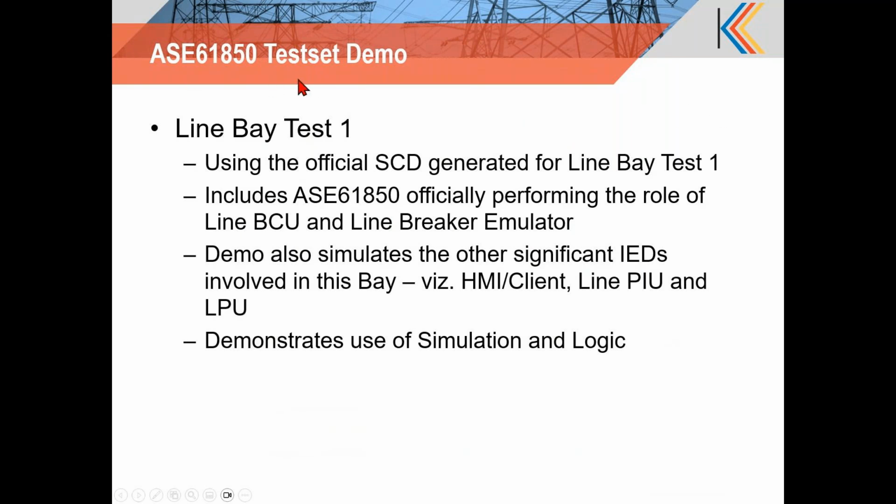Coming to the ASE 61850 Test Set demonstration, today we can see the line-based test capability. Here we will use the SCD file generated for line-based test 1, and it performed several of these capabilities, but for demonstration purposes, we don't have the other IEDs right now. So we will be simulating some of the other IEDs during the demo.